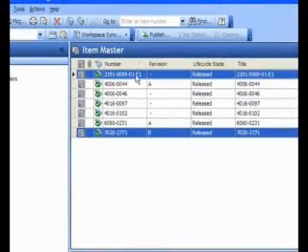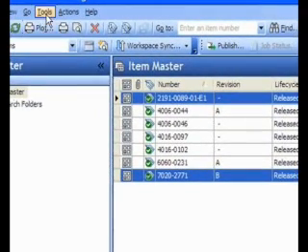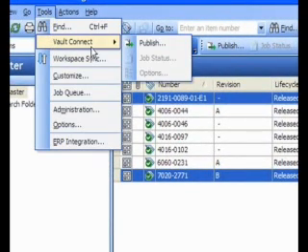Within Vault Manufacturing, the 2 records have been selected. From the Tools menu, you have a Vault Manufacturing menu option. By selecting this option, you see the Publish function. Vault Connect can be set up to publish by either an intentional push or automated. In this case, we are doing an intentional push for demonstration purposes. But we could just as easily set up Vault Connect to automatically query for everything that has been recently released.